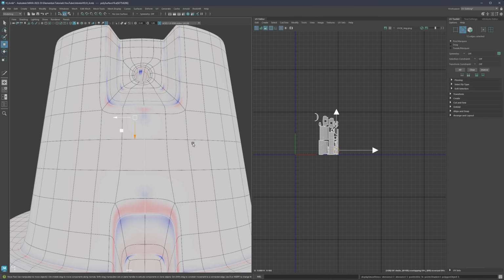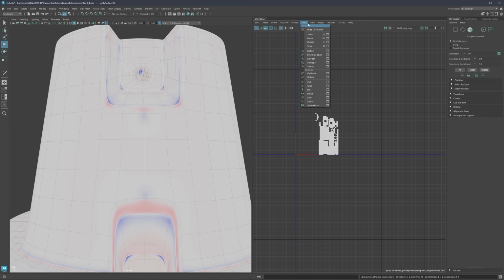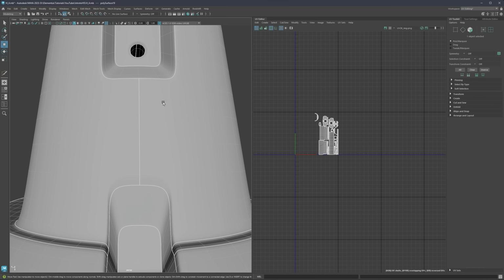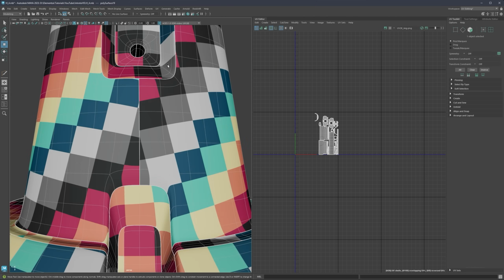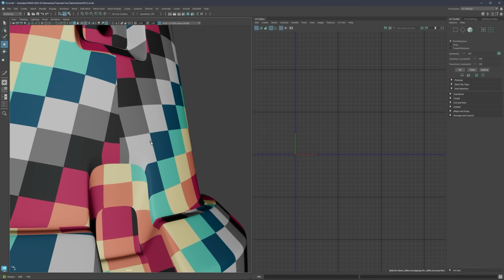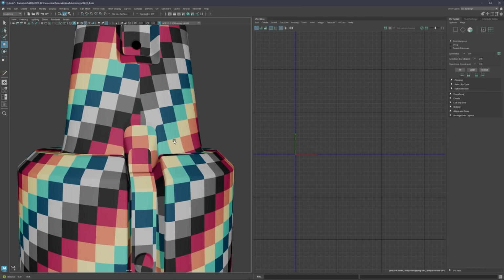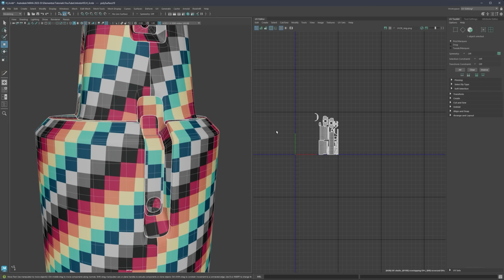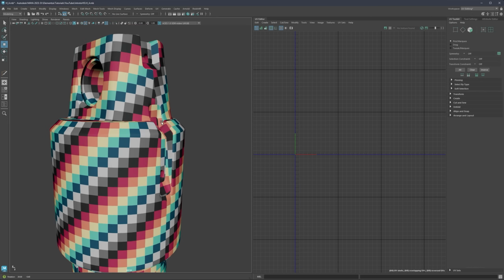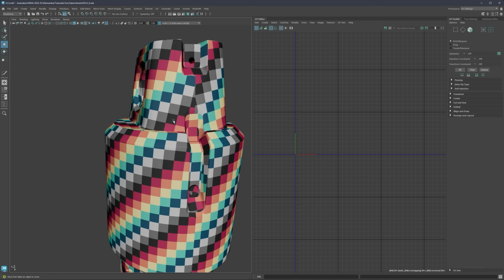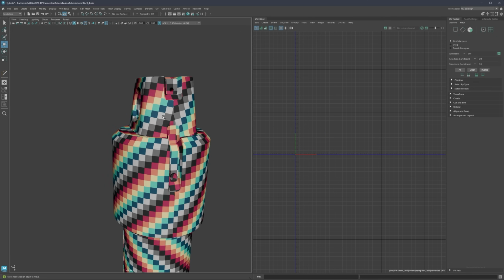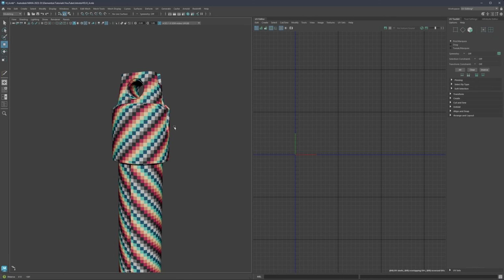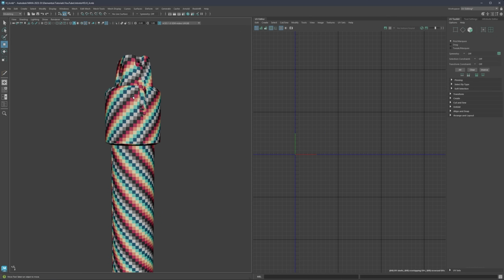So we might see a bit more stretching there, but if we turn on the UV distortion and preview this with the texture, and the texture is performing decently, then we can leave it. But later down the line in the texturing process, if you see serious stretching, you can always come back and either add those loops or add more topology in the middle to alleviate some of those problems. But in general, so far, I think that is going to be fine.